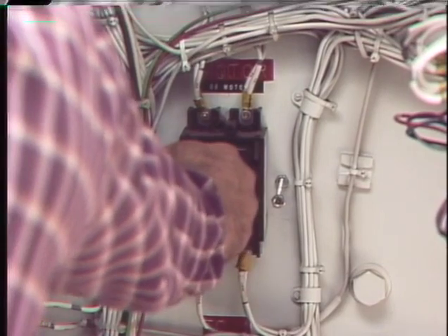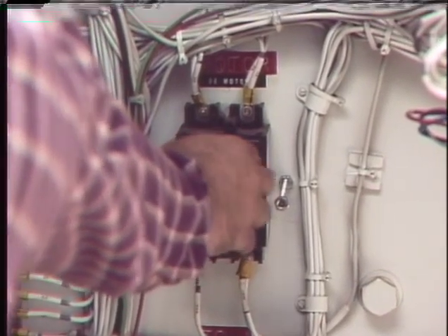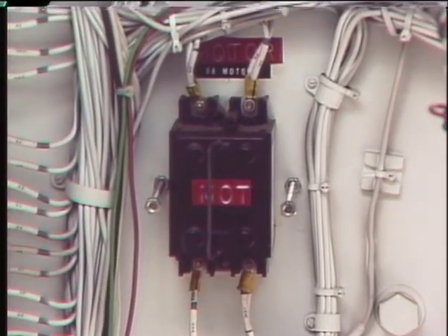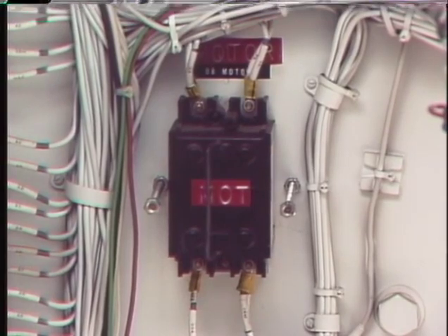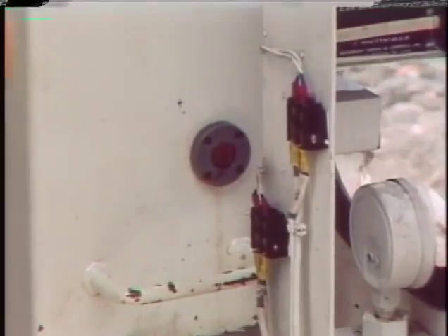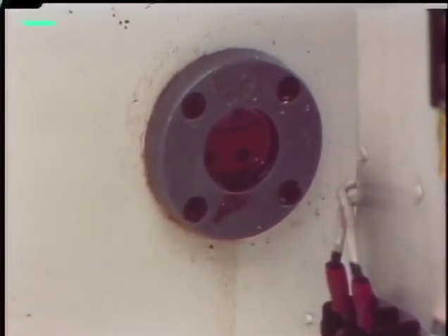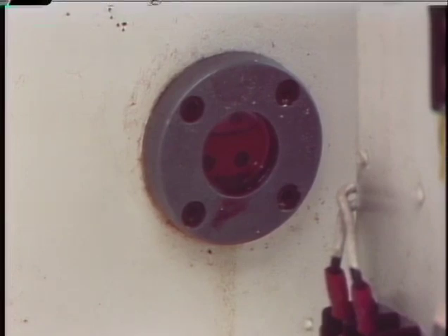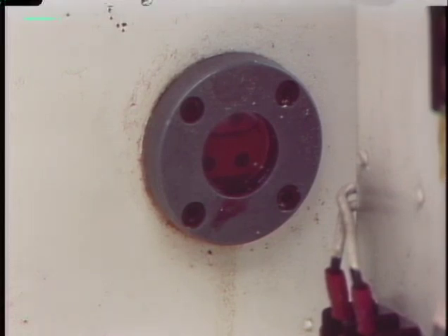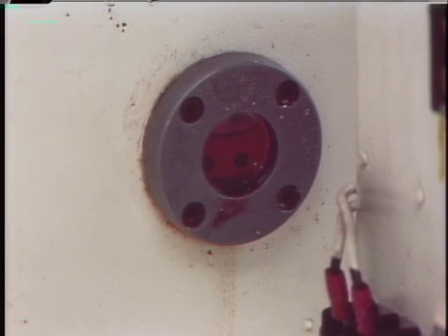After the pre-charge pressure has been checked and gas added, if needed, the motor can be re-energized to restore system pressure to normal. With system pressure at normal, another fluid level check should be made. This time, a sight glass at the bottom of the reservoir is checked. Fluid should be visible. If it isn't, bleed the system to zero and recheck the level at the upper sight glass. Then recheck the pre-charge pressure.